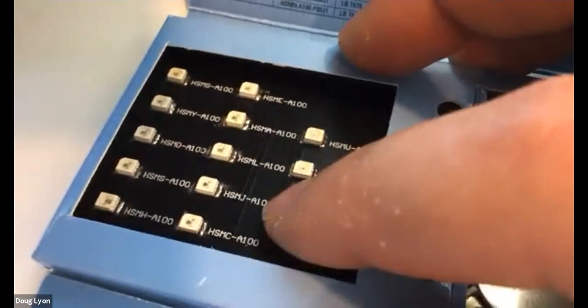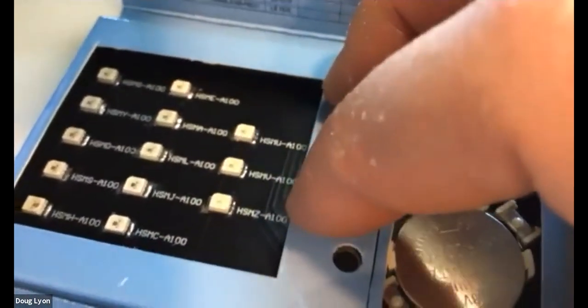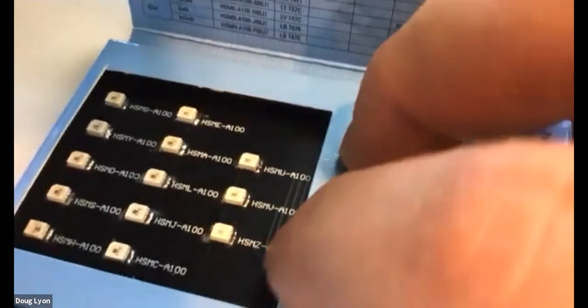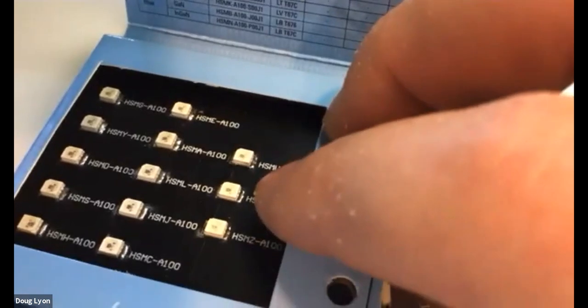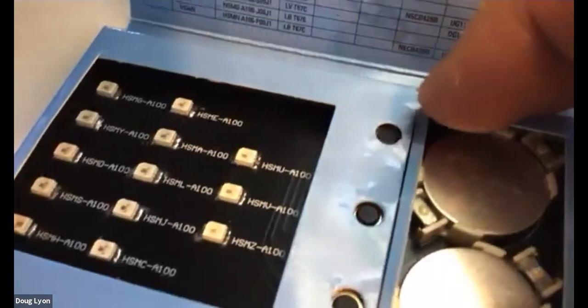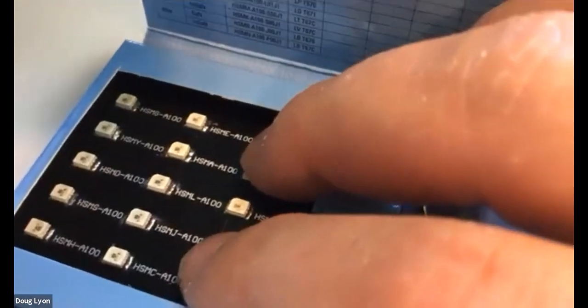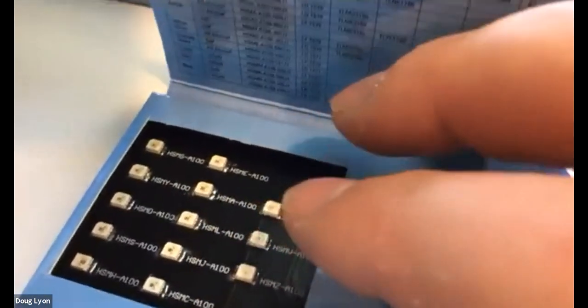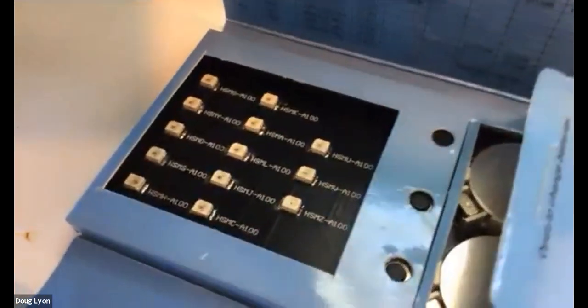Then it goes through the oven called a reflow oven, and it heats the solder so that it melts. Because there are these pads that accept the solder and a wetting agent called flux, it sucks the little surface mount device right onto the printed circuit board, so you don't have to solder individual leads. You basically can solder the whole board at once. And these LEDs, light emitting diodes, they're a little bit different from what we're used to.